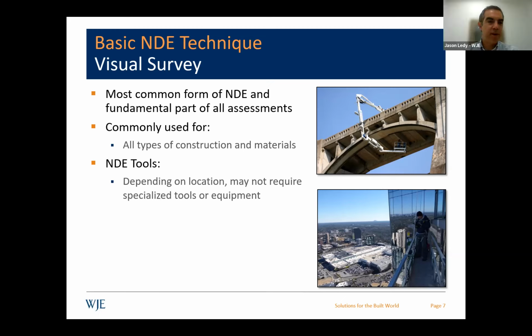If those are not available and the structure is relatively far away, there is the opportunity to use, say, binoculars and telephoto lenses to evaluate a structure from a distance. There are obviously limitations to that. It's much better to be up close and hands-on to do visual surveying.